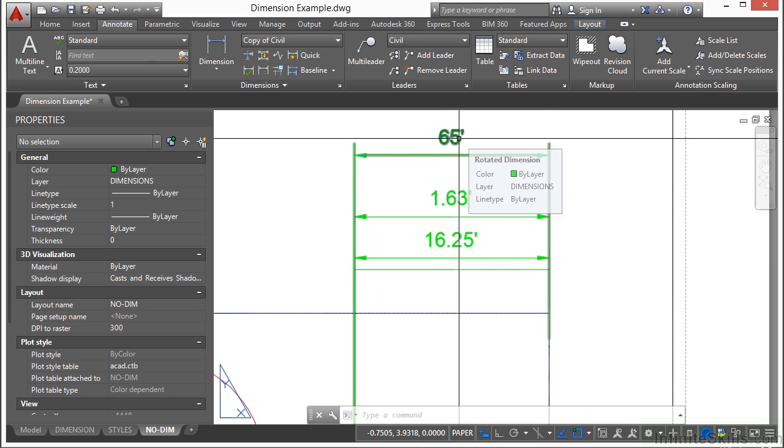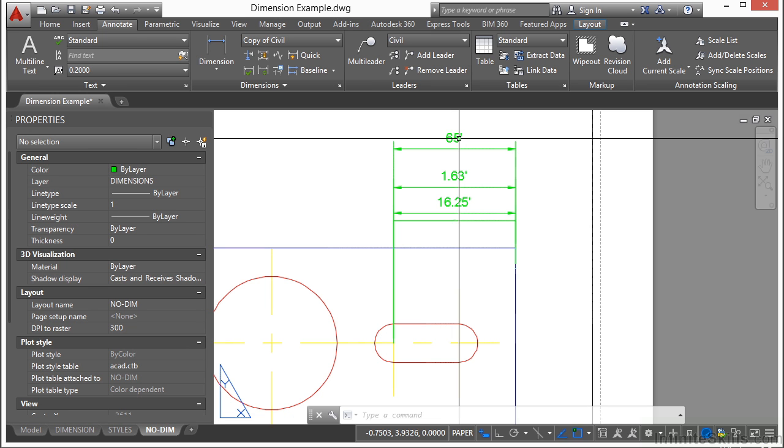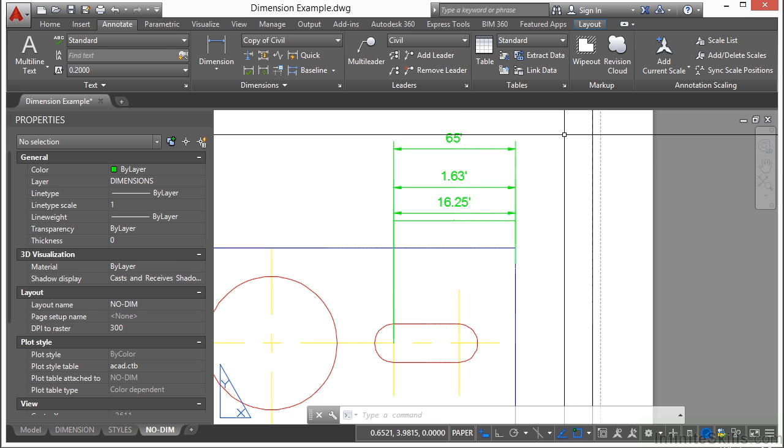Setting 2 is easier because if I have multiple viewports at different scales, which you will often do, especially on architectural drawings or mechanical drawings, then I don't have to set that up. I can just go with it. Also, the setting of 2 works everywhere. It works in paper space, it works in model space. Some people prefer to dimension in model space, some people prefer to dimension in paper space, and sometimes you may have a need to do both. I don't suggest that, but sometimes that happens. Setting it to 2 means there's less work for you to do.